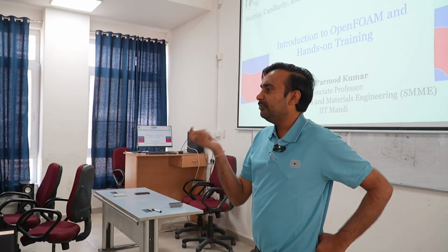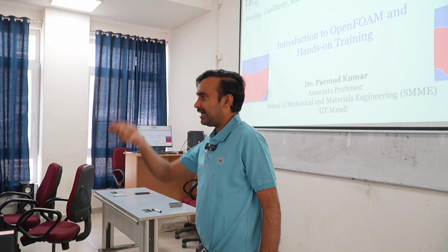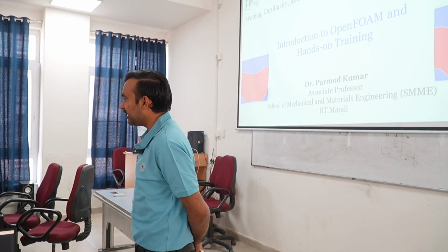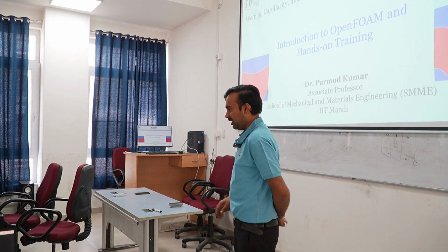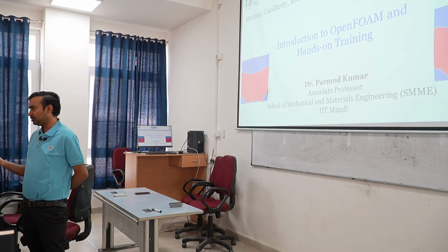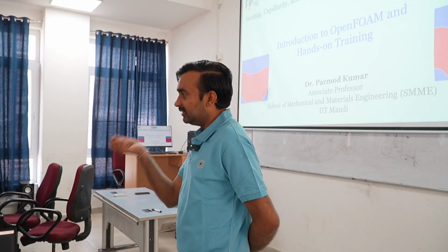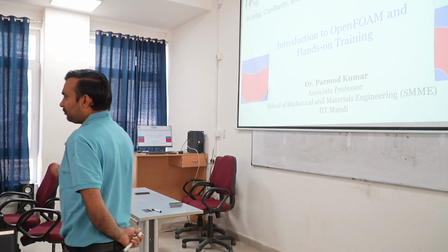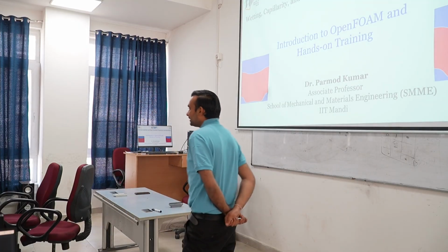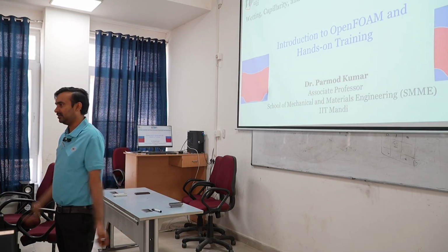So ultimately, we need to modify the momentum equation in such a way that I can incorporate the gradient of surface tension along the interface. In that case, I need to do some modification to my governing equation. Majority of the time with commercial software, the source code is not available to the users and we cannot do these types of changes. Of course, these provide some flexibility in the form of user defined functions, where for certain terms you can use user defined functions which can assist in these situations, but we cannot do significant changes in the code because it is not available to us.